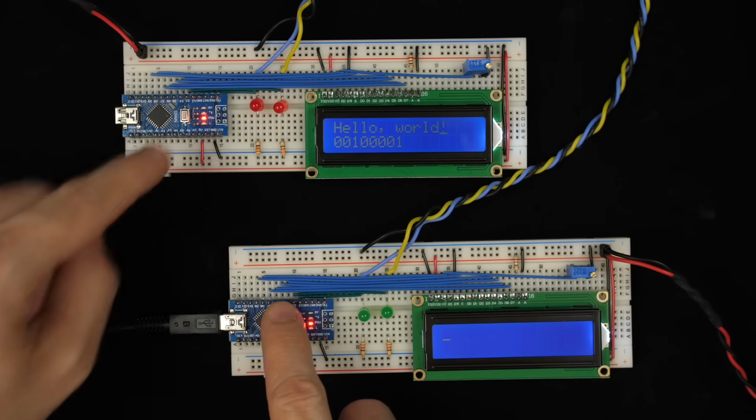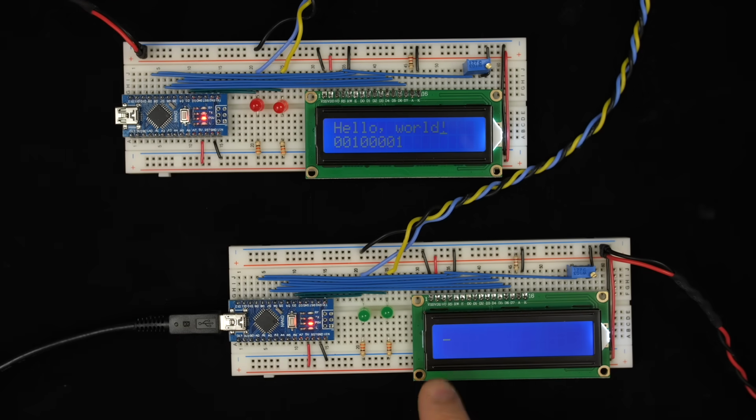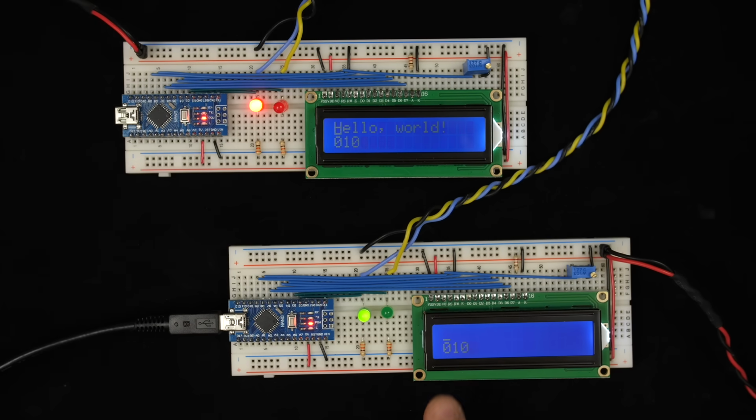And so we don't have to worry about keeping them in sync by resetting both of them at exactly the same time. So it's already just waiting for that first bit of the first byte. So if we just reset the transmitter, then as soon as it starts sending, it starts receiving a byte, and the byte is always going to be aligned just perfectly.